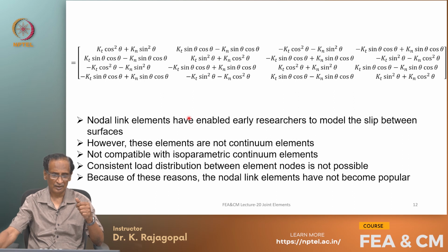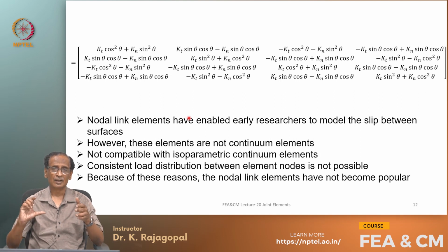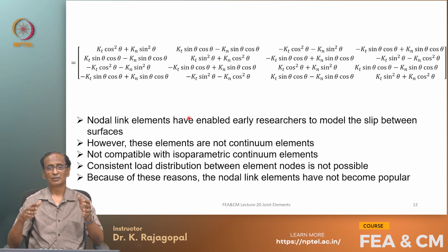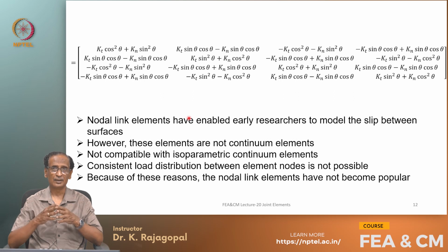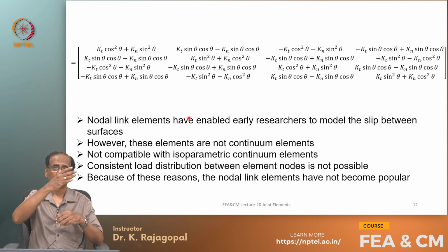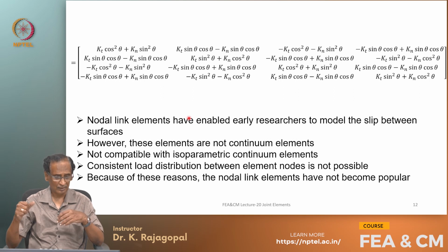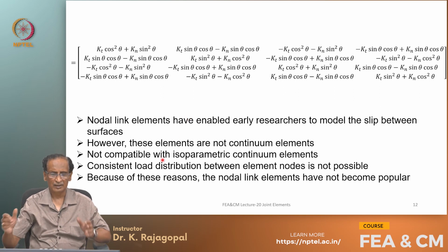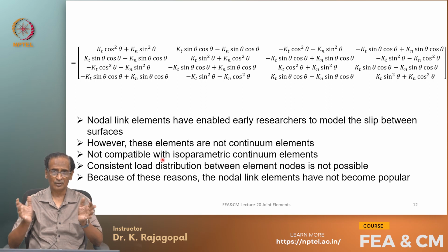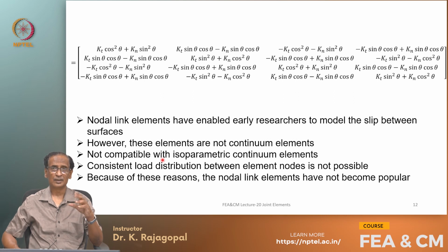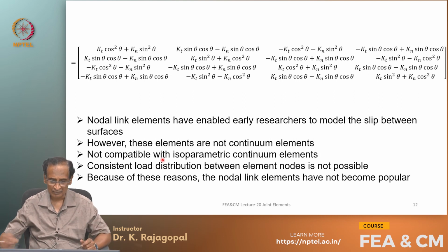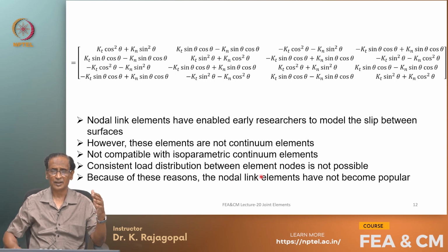But when we use these nodal spring elements, we need to externally compute these stiffness coefficients, and that may not be possible, especially if you have a curved surface. How do we deal with the stiffness, because that depends on the curvature and so on. And we cannot get a consistent load distribution between the element nodes by using the nodal spring elements along with isoparametric elements.